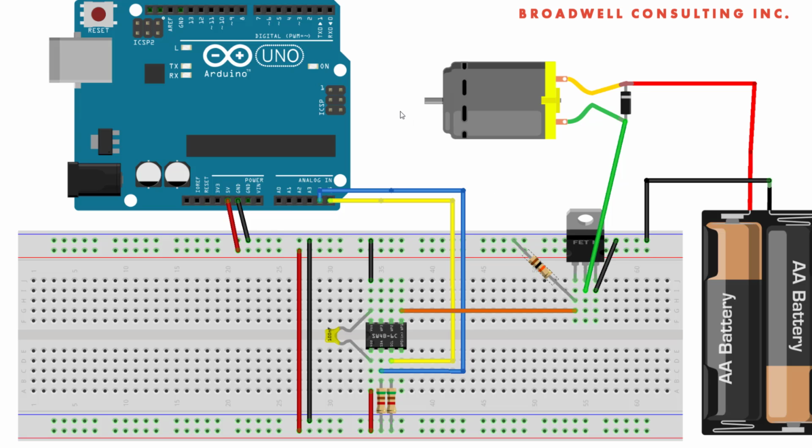Another use for the Serial Wombat Watchdog is to use it as a pulse that will automatically shut off. Imagine for a moment that we have a motor that's being driven by the Serial Wombat, and something bad could happen if that motor continues running in the event that the Serial Wombat loses connection with the Arduino, or that the Arduino fails to send a command to shut it back off when it's finished. We can use the Watchdog output as a digital input-output that will shut off itself if not commanded to stay on periodically. In this case, we would say we want this pin to be low as a reset result, but high during the normal operation.